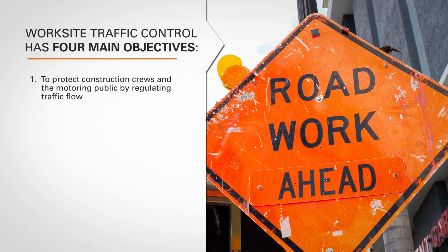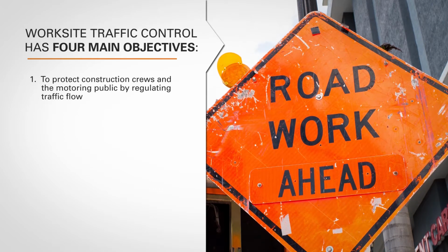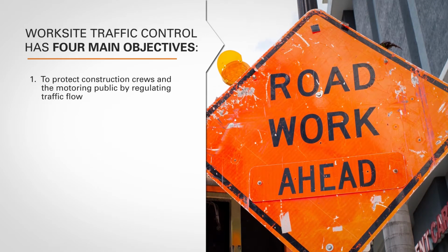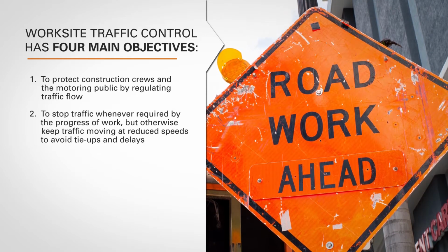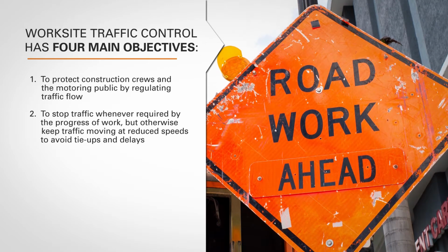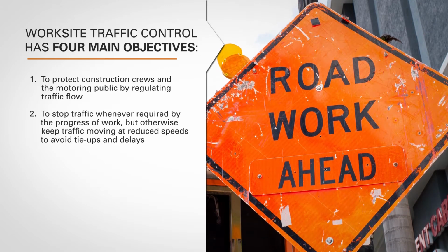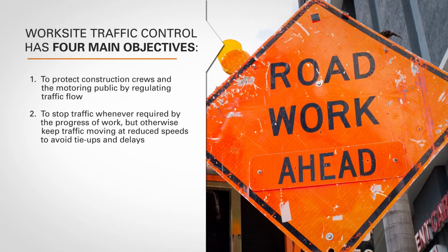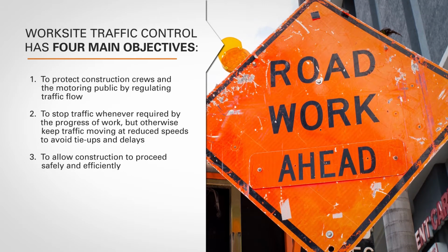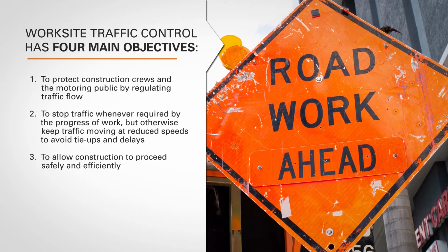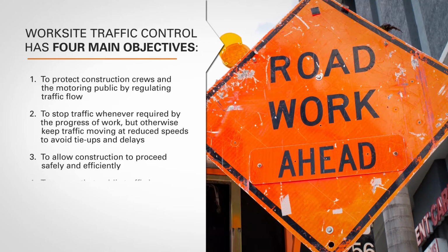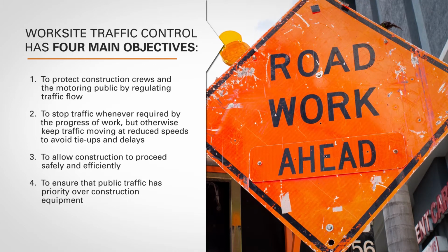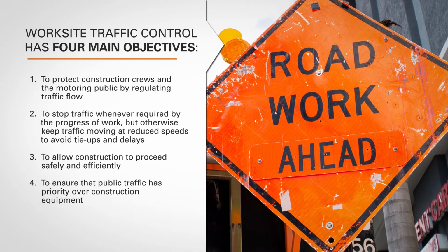1. To protect construction crews and the motoring public by regulating traffic flow. 2. To stop traffic whenever required by the progress of work, but otherwise keep traffic moving at reduced speeds to avoid tie-ups and delays. 3. To allow construction to proceed safely and efficiently. And 4. To ensure that public traffic has priority over construction equipment.